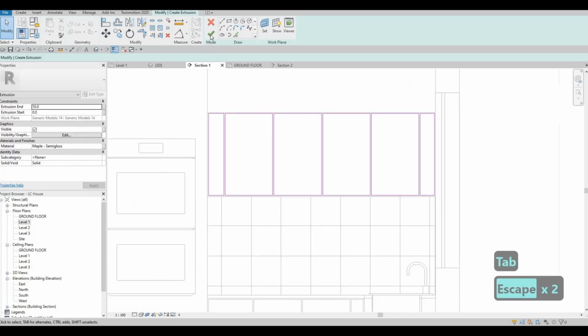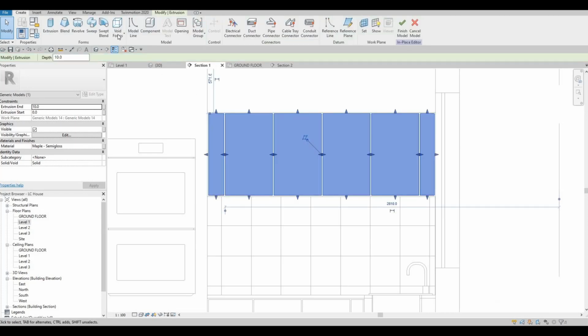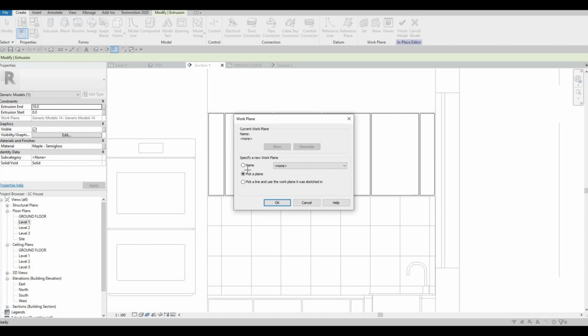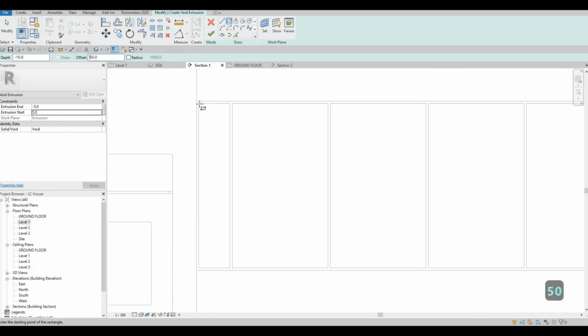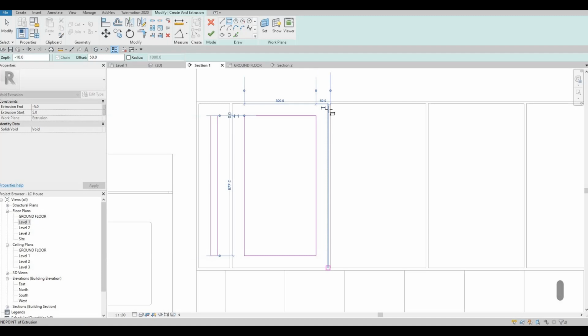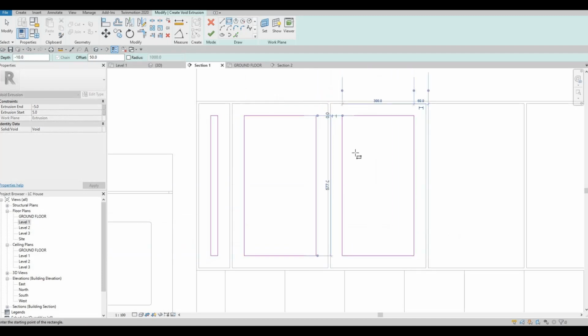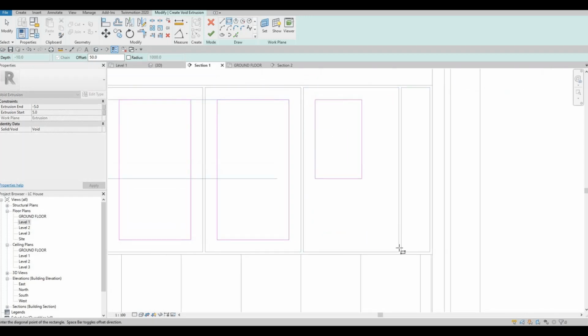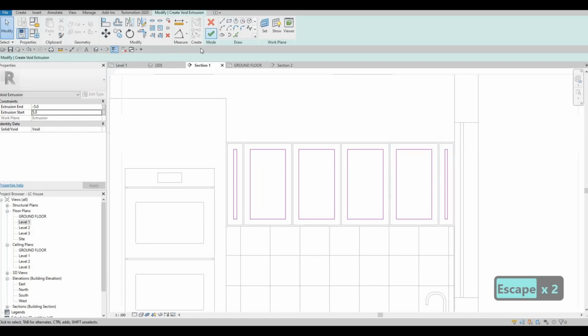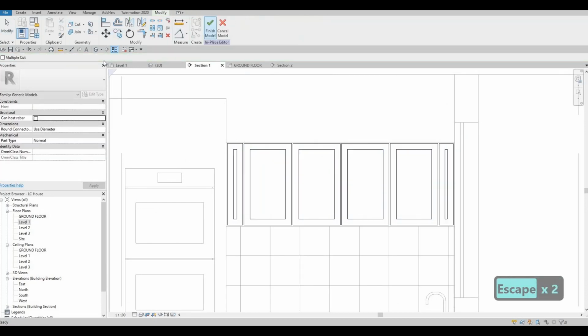that's 10 as well. So click finish, and then don't click finish yet because we need to void this extrusion, and then select this plane, and then do the -5 and then 5, and then rectangle, and then 50 offset, and then we're going to offset it through the inner, and then click on finish, and then you can cut geometry and finish again.